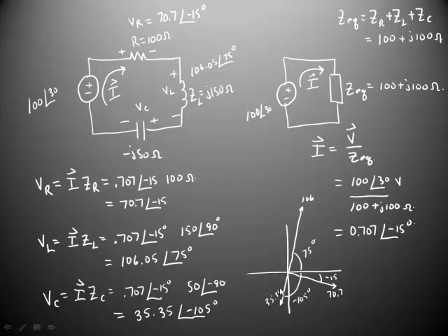And then, of course, we have to account for the voltage from our source, which has a length of 100 and makes an angle of 30 degrees with the real axis. I'll leave it as an exercise for the student to take these four vectors and see to it that they do in fact sum to 0. And that's all you need to know about simple circuit analysis with phasors.